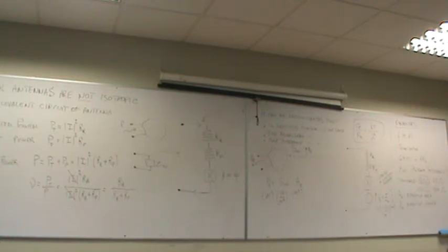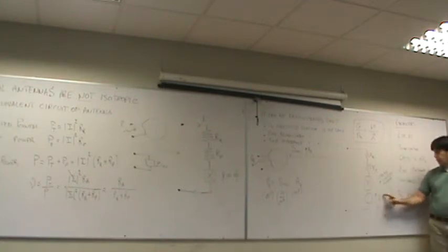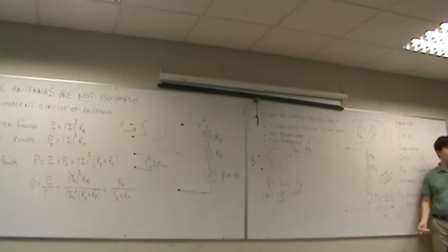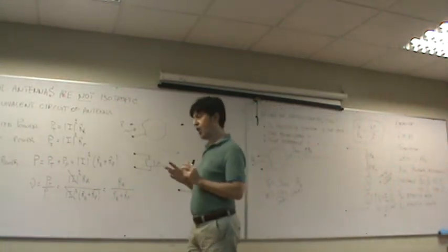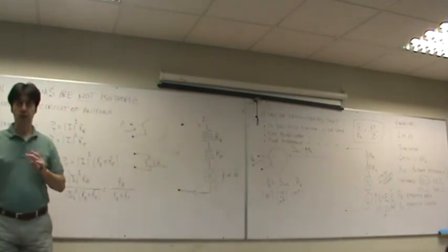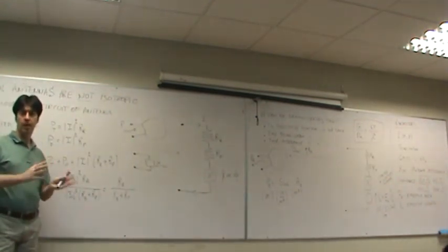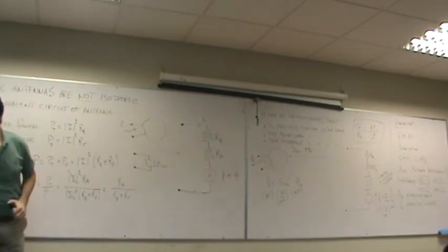Fields, currents, voltages, all phasors. So, if the length is a complex number, what does it mean? It means simply that the voltage is not in phase with the electric field. Nothing special. So don't worry if the effective length is a complex number. It just means that there is a difference in phase between the electric field and the voltage.